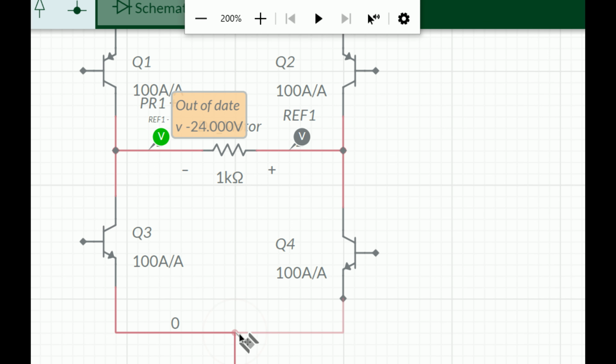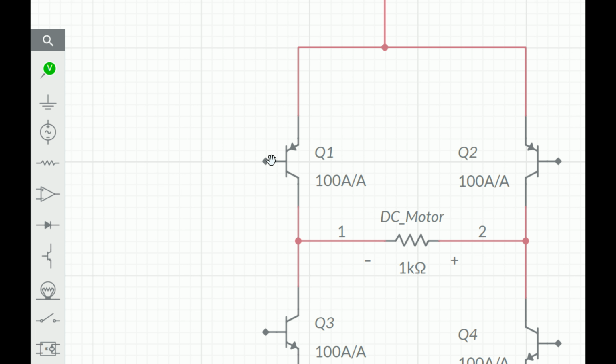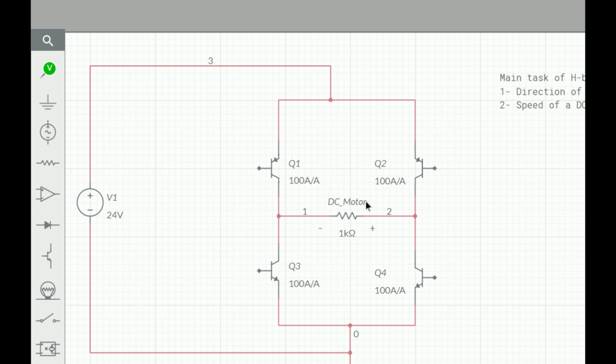How? Because now this over here is our pin, the base pin of the transistor, or the gate pin in the case of a MOSFET. This is for the BJT, the base pin, and for the MOSFET it will be the gate pin. It goes to our microcontroller, and the microcontroller or any controller that we are using, like a PLC or Raspberry Pi, can generate the PWM frequency, and that frequency of 5 kilohertz, 10 kilohertz, whatever we give to the transistor will control the speed of a DC motor. So that's how we control the speed of a DC motor using the PWM at the base or gate pin. Now let me show you how this circuit works.